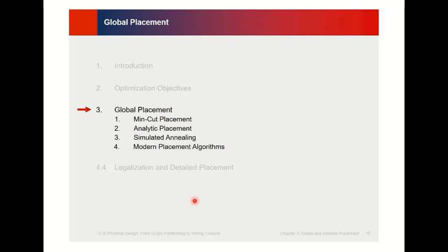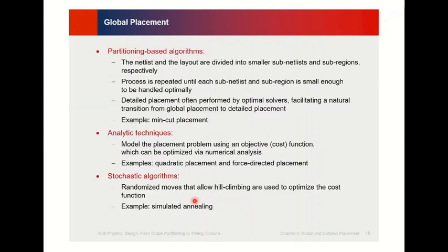For a global placement algorithm, there are many algorithms, which are loosely classified into partitioning based algorithms, analytic techniques, and stochastic algorithms. You are familiar with stochastic algorithm. Usually it will involve simulated annealing.